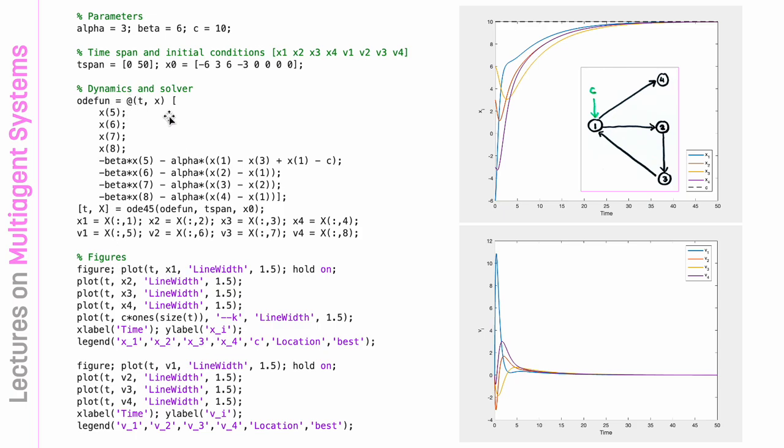This is basically an ODE running the same algorithm. x dot equals, these are the four agents' position states, the position dot equals velocity, for 1, 2, 3, 4. It goes like this, so I use this convention. This is the entire ODE that I am simulating. The first agent is the leader, that's why it has access to the command, and these are the figures. I am simulating it with ode45. So as expected, the position states of each agent converge to 10, and velocities become 0. Once agents approach their position commands, the velocity becomes 0.